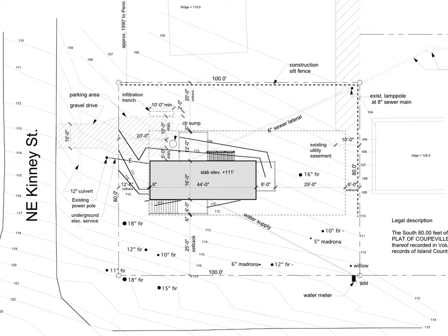In the front of the house, you'll notice the way the contour lines angle away from the house, and what that's trying to do is essentially create a little swale at the front of the house. If the slab elevation is at 111, there's actually a little retaining wall there because it's below grade, and you'll see that the 113 and the 112 contour lines die into that retaining wall, foundation wall, and there's a lower point on that side of the house to try to direct the water around the house rather than running into it.